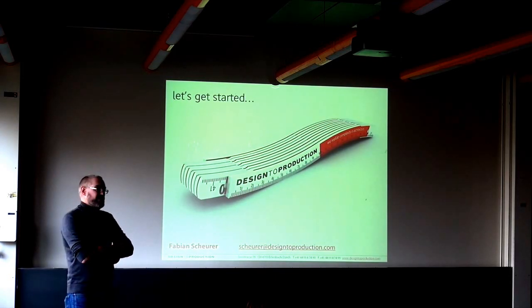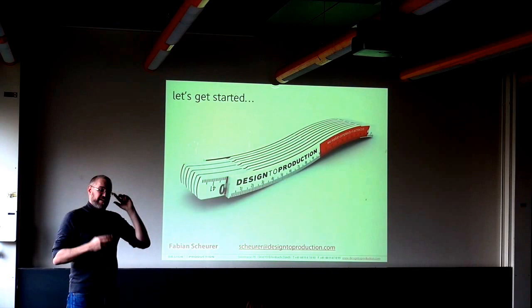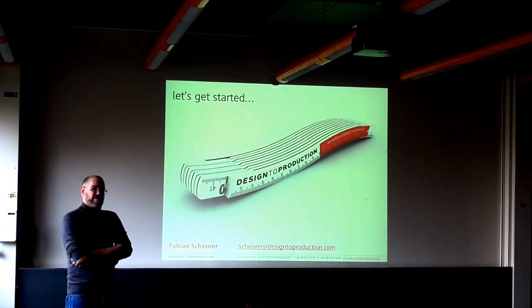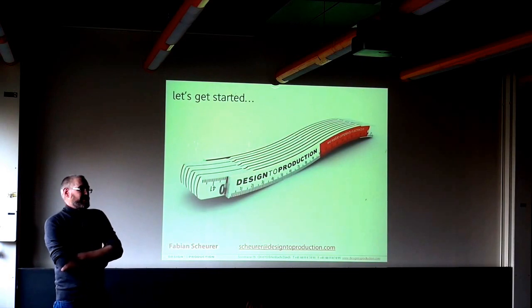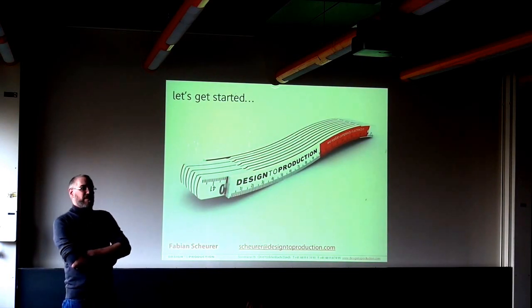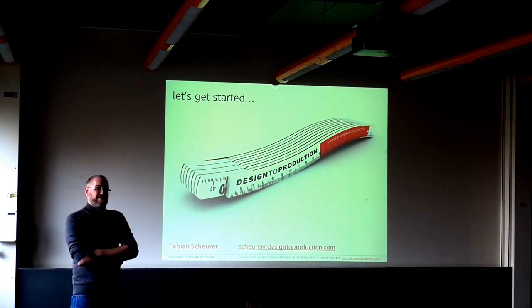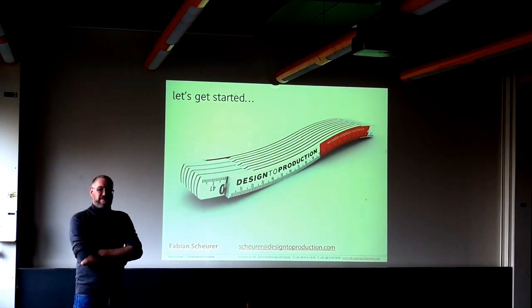Which means, and this is why we hardly ever have any 3D volumes of finished components in the model. It just doesn't make sense. It's much easier to just store the drilling axes and then hand that over to a fabrication machine that just drills a hole there with the right drilling bit and the right diameter. Why should I generate another volume object and representation that I carry around with me all the time, other than for visual checking?